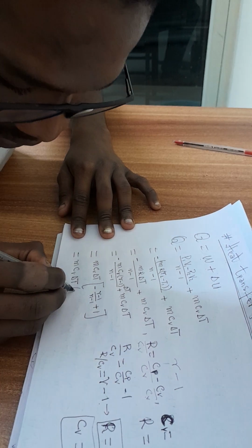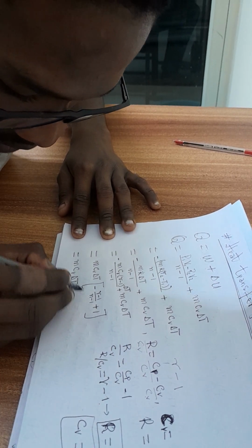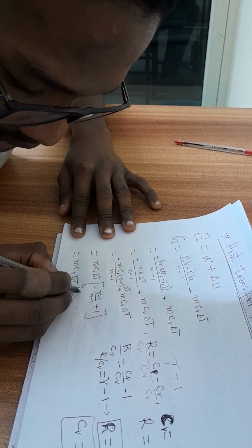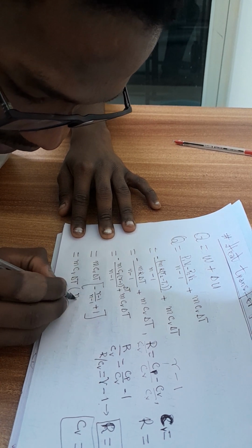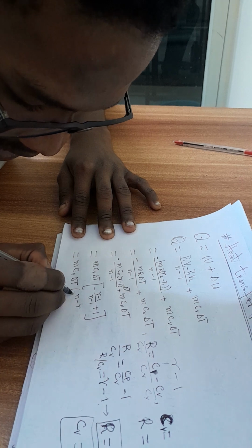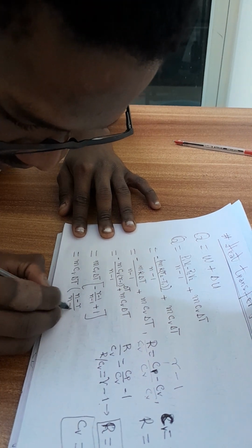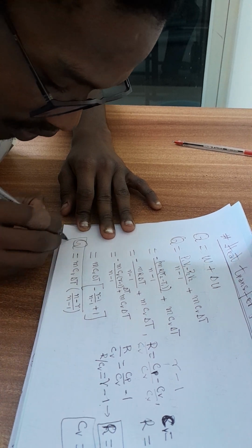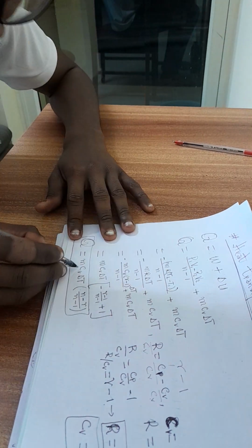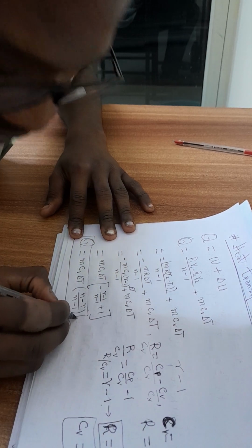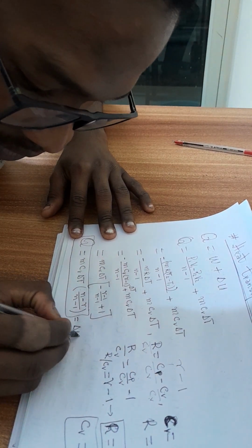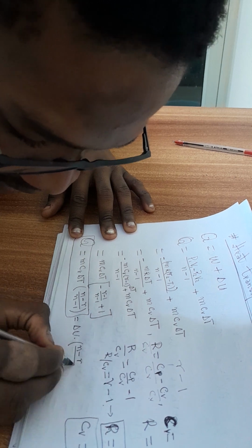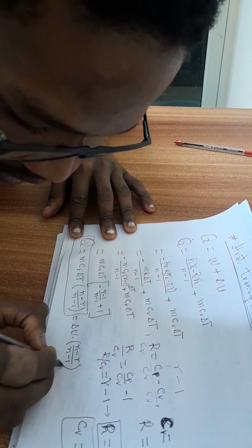This is simple math. You will end with (n minus gamma) upon (n minus 1). So the heat transfer is m Cv delta T times this, which is the same as delta U, so it will be delta U times (n minus gamma) upon (n minus 1).